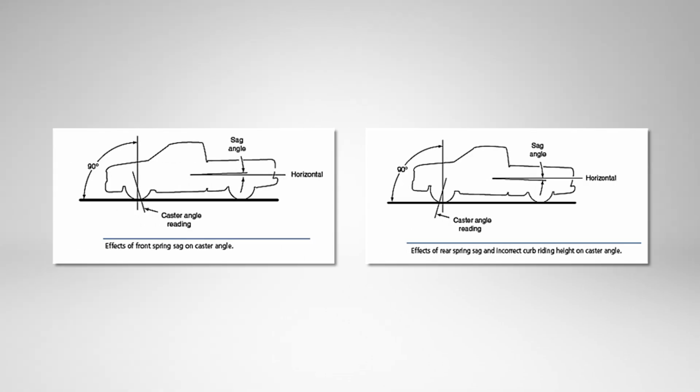A caster value deviating from spec can have several causes. Caster error at both front wheels can often be traced to the relationship between caster and the level of the vehicle. By raising the rear of the vehicle, caster shifts to negative, and by lowering the rear of the vehicle, as in sagging springs or overload conditions, caster shifts to positive. Large individual caster errors suggest possible bent or overworn suspension components or even structural damage.